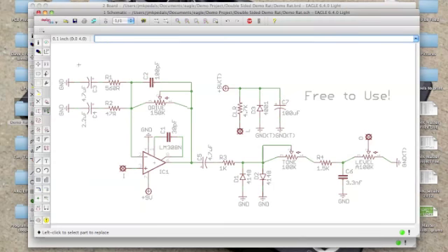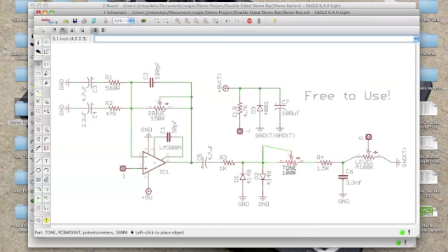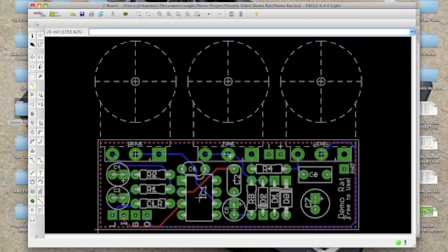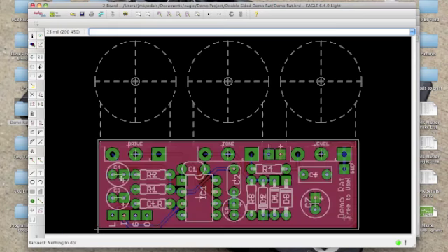So obviously our graphic interface is a little bit different, so it's actually messed everything up graphically, not schematic wise, but certainly graphically. So once all these connections, all those changes are done, notice it didn't change the name or the value, it just changed the symbol a little bit. And as we go now to this, check it out. The pads are a little bit bigger, the numbers in a different spot, our graphic interface is a little bit different. As I press my rat's nest button, right?